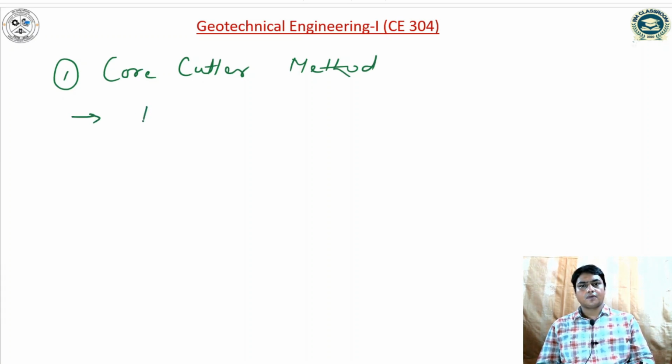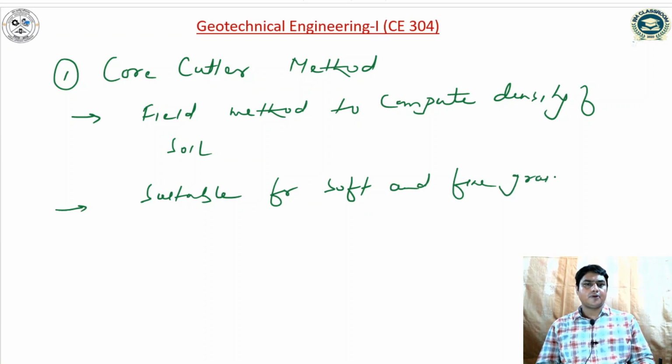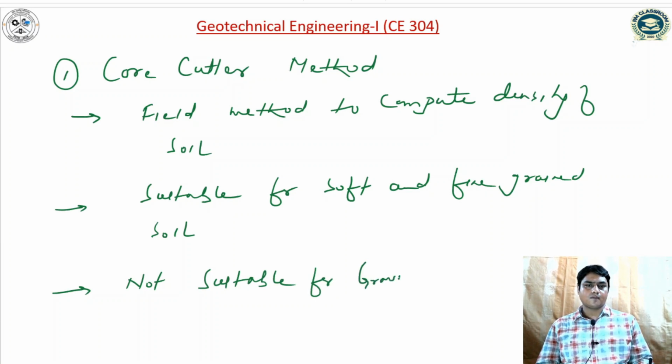This core cutter method is a field method to compute density of soil. It is suitable for soft and fine grained soil. It is not suitable for gravelly strata.